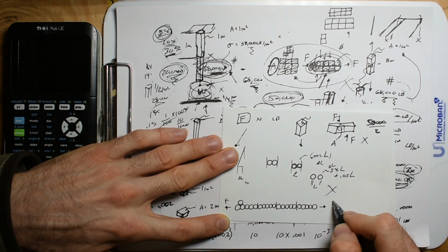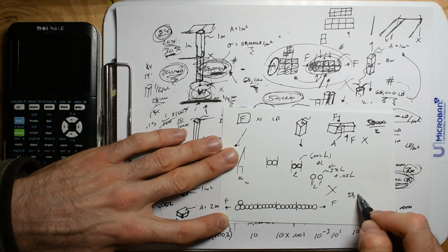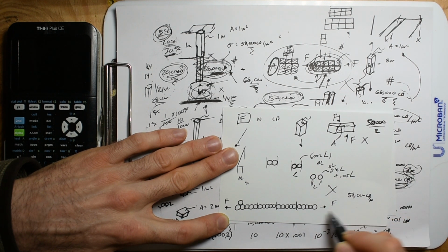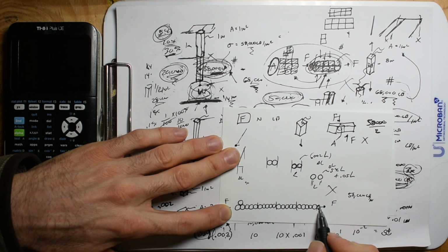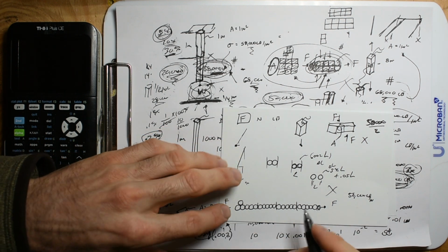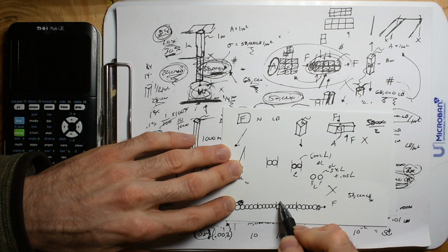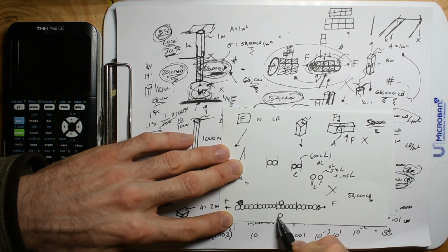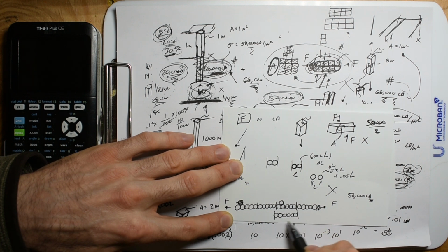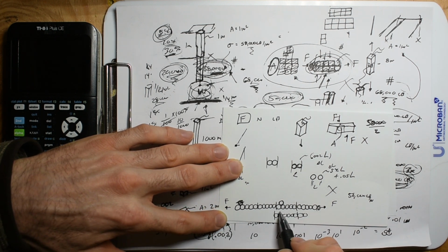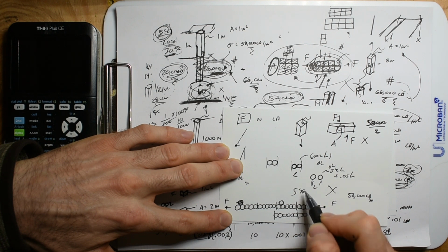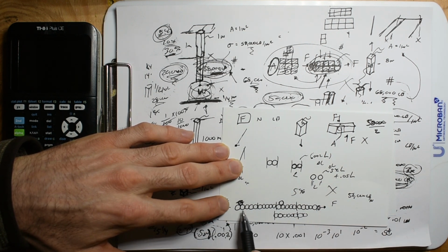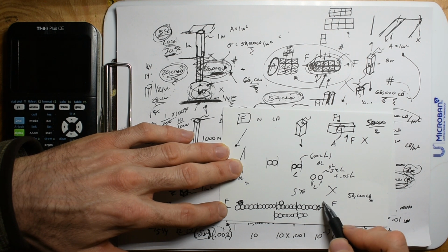But when I yank on this thing and get it up to that 58,000 pounds per square inch in whatever surface area this was, guess what's going to happen? No matter where I put this, we can put it right here if you want. This is going to squeeze in the gap, so it's going to occupy that space. And now right there I'm going to have 1, 2, 3, 4, 1, 2, 3, 4, 5, 6. So that's going to be in that space. And that would be a 5%. You know what I mean? That would be an example of a 5% increase in length.